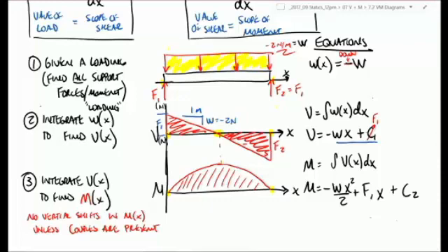I had a vote of F2. Any other votes? What's the value at the start of the moment curve? 0. Right? That's all those constants are. It's the value at the start of the function. It shifts it vertically if you didn't start at 0. And so this one here is 0 because we started here at 0 for that moment curve.